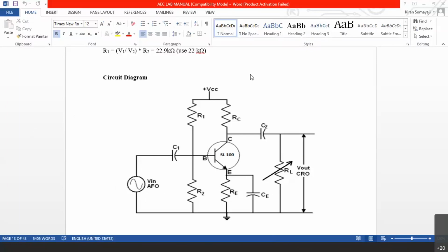Tell me how? By using the multimeter, I'm finding the total resistance. Which resistance? No. We have this 2.2 kilo ohms here. We have 470 ohms here. Those are biasing resistors. How do we check that the transistor is exactly in the Q point?